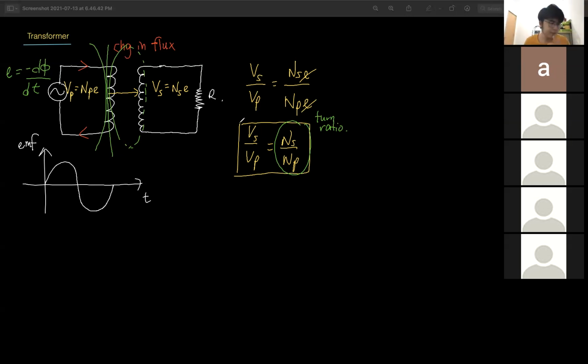Let's say you want to power your microwave at 2000 volt. You put it where? You put it in the secondary circuit, right? Now, the primary circuit is the one that you put in the socket, right? So that is 240. Let's just take 200 for easy calculation. So the voltage I need is 10 times greater than this 200.